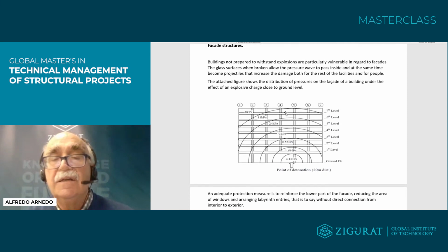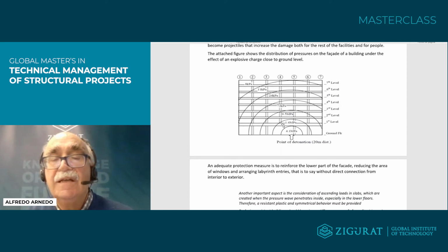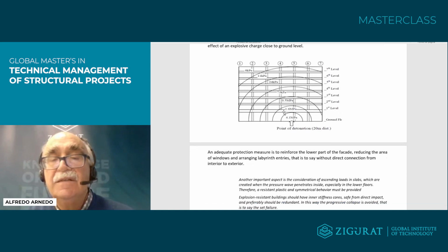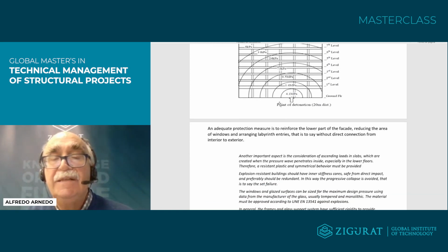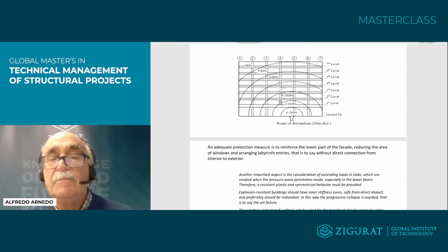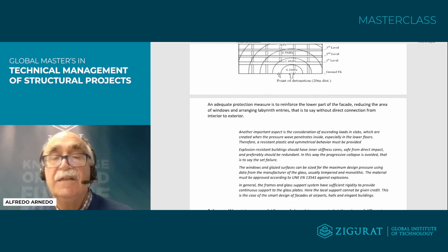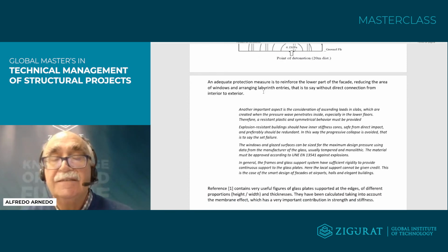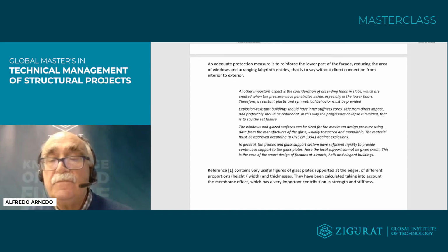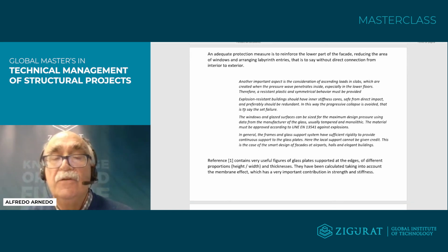Another point is that when the modules of the facade disappear, the explosion comes into the building and produces uplift pressure. Usually the slabs are not prepared for this. So this is the same advice, to be prepared for the forces to change even in a slab, not only for vertical descending loads, but also for ascending, for uplift.